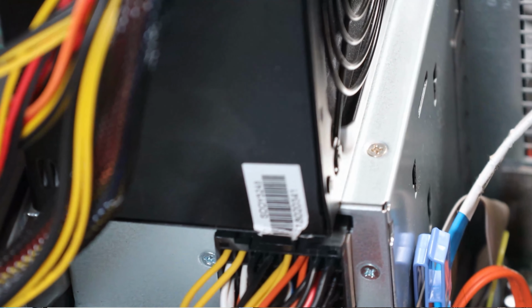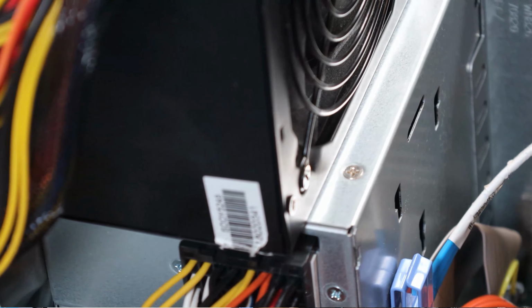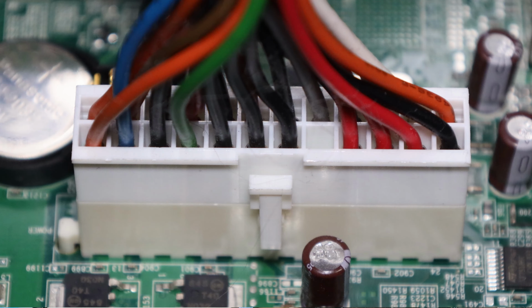Depending on the computer, it may have the same connectors as the ATX standard. In this example, the P1 connector is the same as the ATX standard. In some cases, the motherboard's main power connector may be different. When this occurs, sometimes you can get a converter cable to convert an ATX power supply to the proprietary connector. However, these cables are rare.